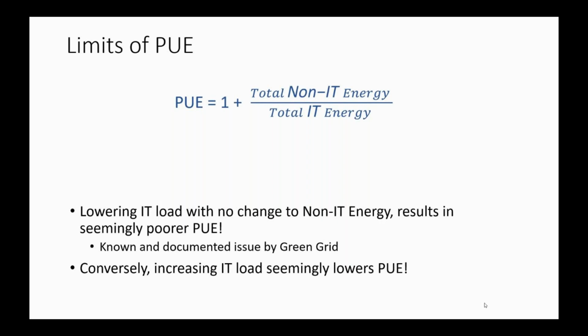So if you only make changes to the IT load, where your whole goal is to reduce your overall consumption, essentially you're measuring across two different IT loads. If you do that, then the PUEs are not comparable. That's the way to think of it, rather than that your PUE went up. So your goal should be to at all times keep your IT load constant, so your measurements can be compared. Otherwise, you run into very contrary problems like this one.